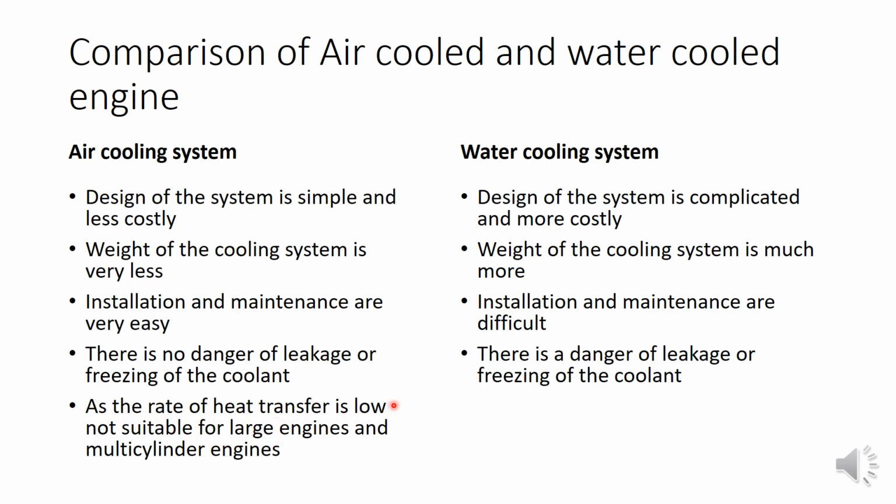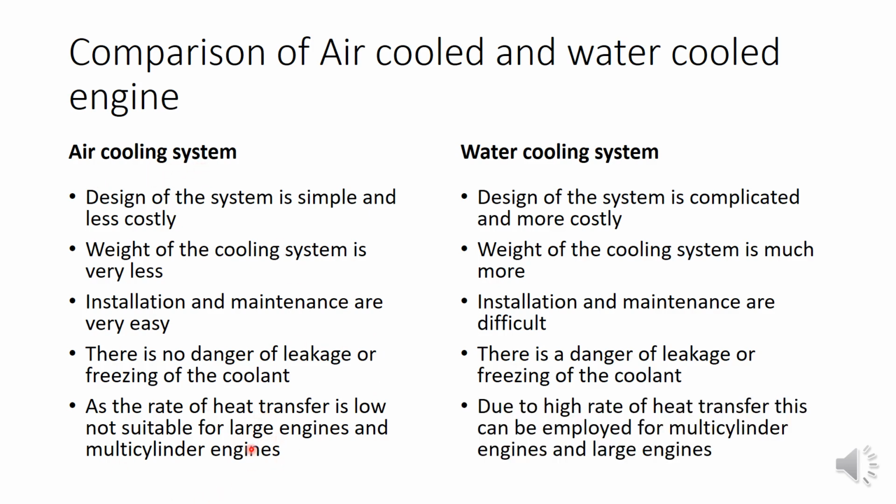So the rate of heat transfer is very low in air cooling system. So we are not able to use it for larger engines and multi-cylinder engines. So in almost all heavy vehicles, cars, etc., we are not able to use the air cooling system due to this reason. On the other hand, in the water cooling system, we have a high rate of heat transfer. So it can be employed for multi-cylinder engines and for larger engines. So this is the main advantage of water cooling system compared to air cooling system.